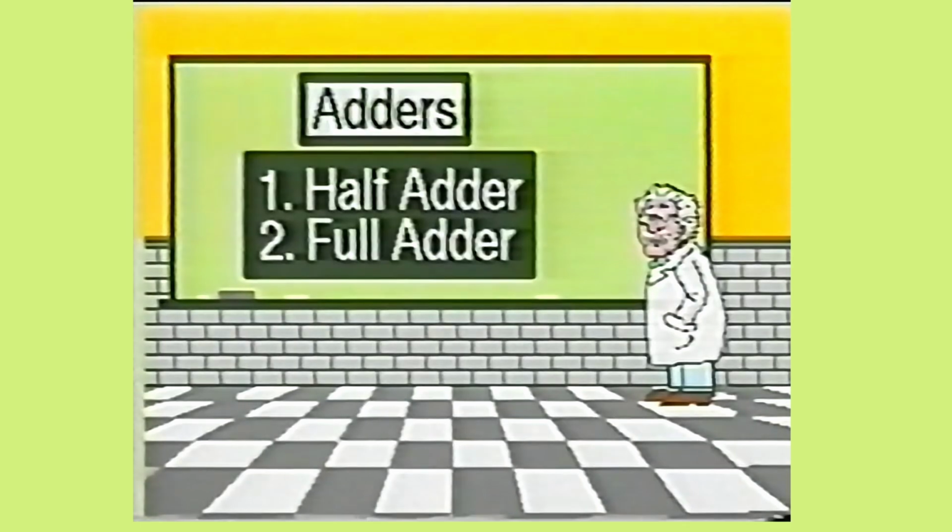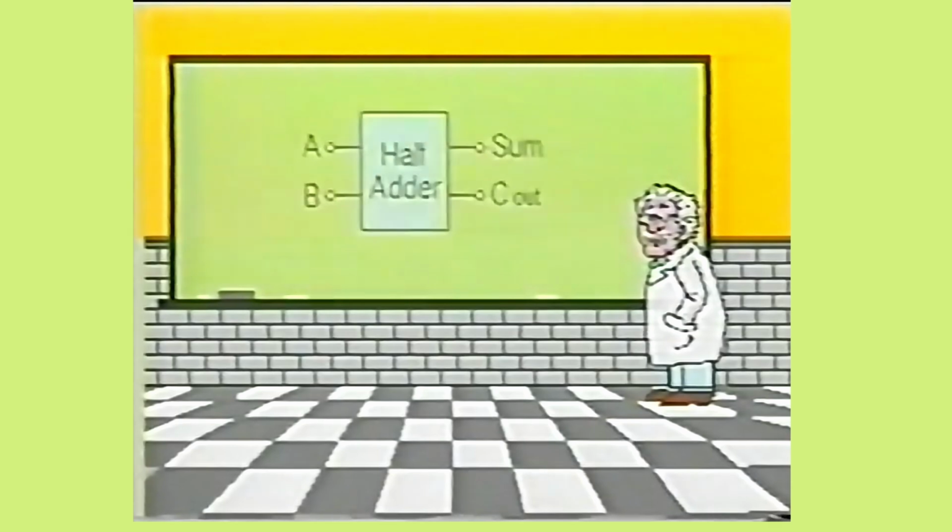You have also seen how two different types of adder circuits work, the half adder and the full adder. The basic adder stage will accept two inputs and generate two outputs. The two outputs are the sum and the carry-out. The half adder will only accept single binary bits to be added. These bits are placed on inputs A and/or B. The half adder is generally used as the least significant stage of a full adder network.